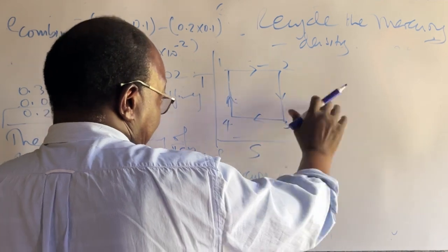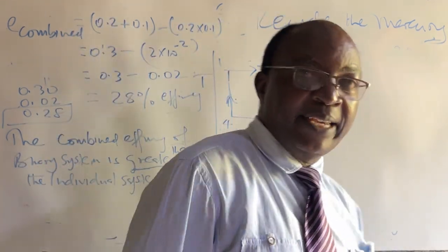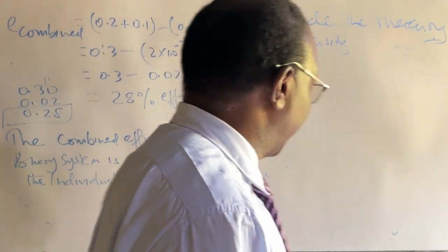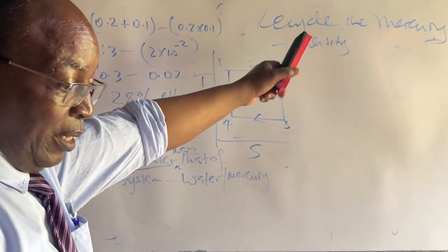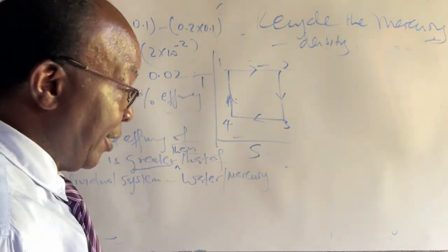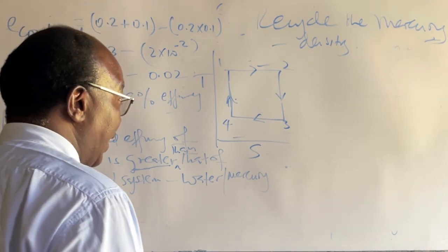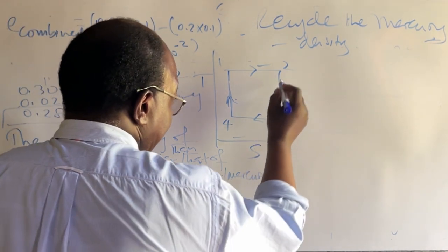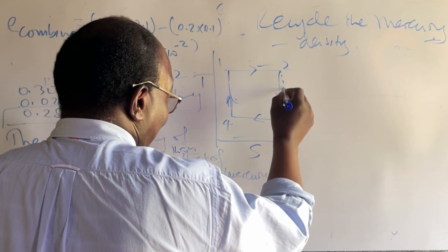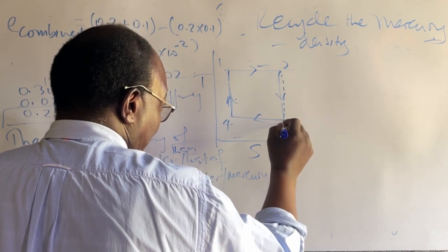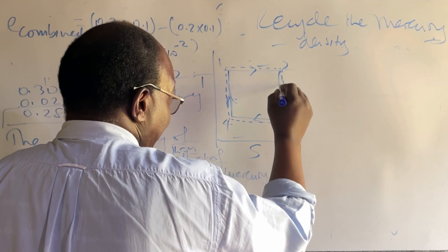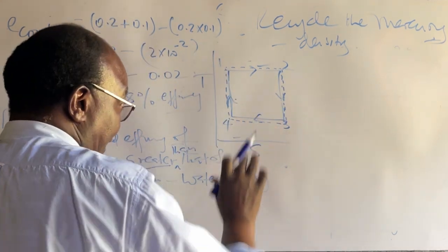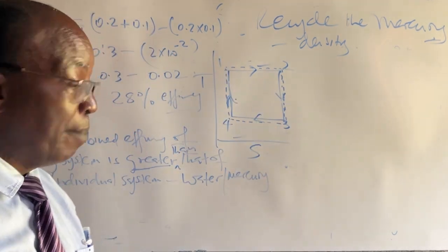Isothermal, isentropic corresponds to adiabatic. They are in the earlier lectures which we have discussed. Now, with the mercury, because of these qualities of mercury, the specific heats and so forth, it approaches this cycle very, very closely. It approaches this Carnot cycle in the temperature entropy diagram.